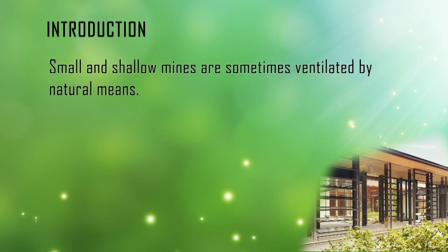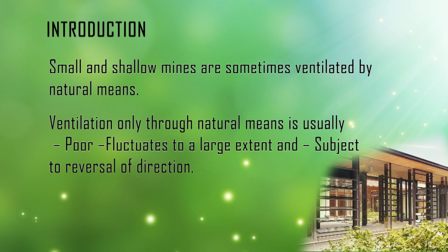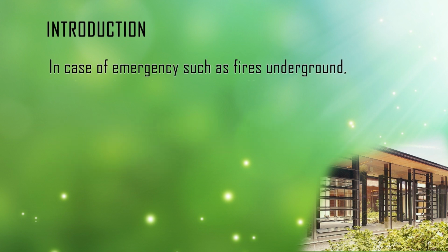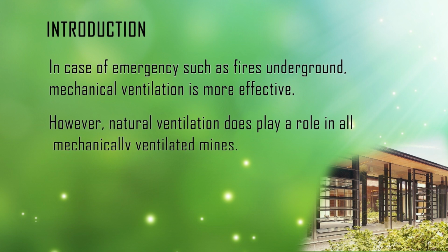Small and shallow mines are sometimes ventilated by natural means. Ventilation only through natural means is usually poor, fluctuates to a large extent and is subject to reversal of direction. In case of emergency such as fires underground, mechanical ventilation is more effective. However, natural ventilation does play a role in all mechanically ventilated mines.